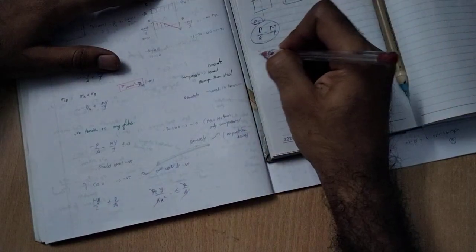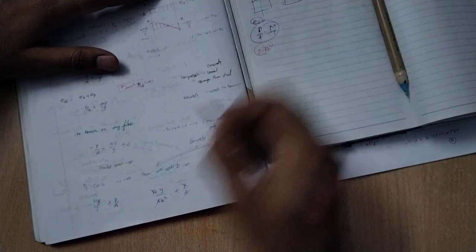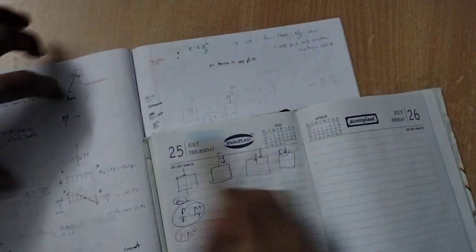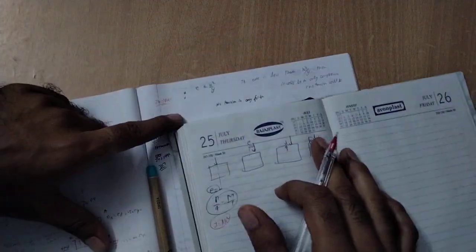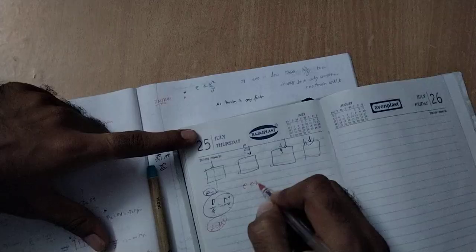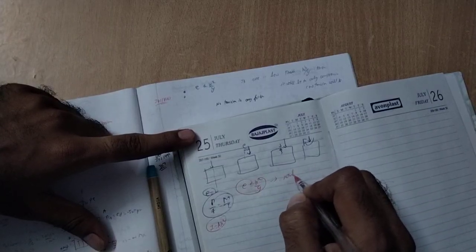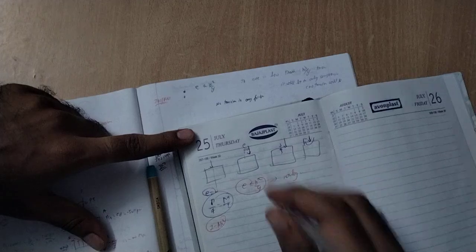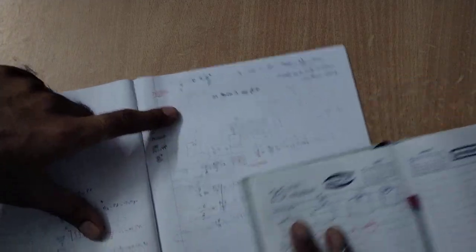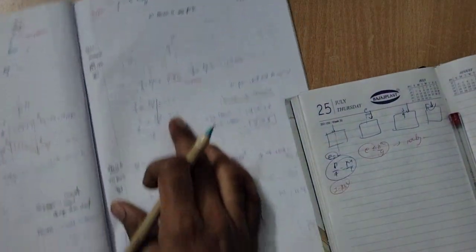So I equal to what we just did, area into k squared. So calculate, and at this load, at the eccentricity equal to less than or equal to k squared divided by y, here the eccentricity is low, then only compression will occur. No tension will be there on this side. These are the questions that will be asked.